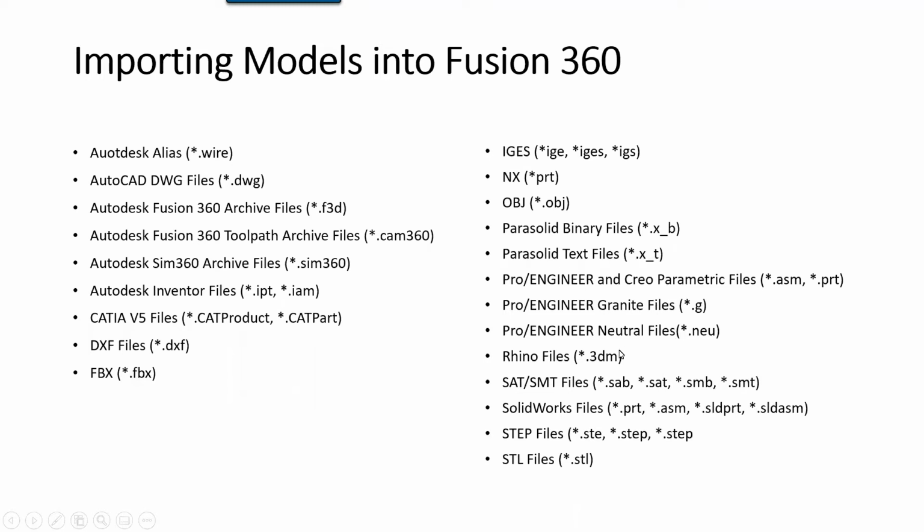So obviously, if you're coming from Pro E, then you're only limited to some of these file types here. But again, if you're coming from something like Revit, maybe SAT, maybe STEP file is going to give you the best outcome. It's just a matter of making sure that you test that out.